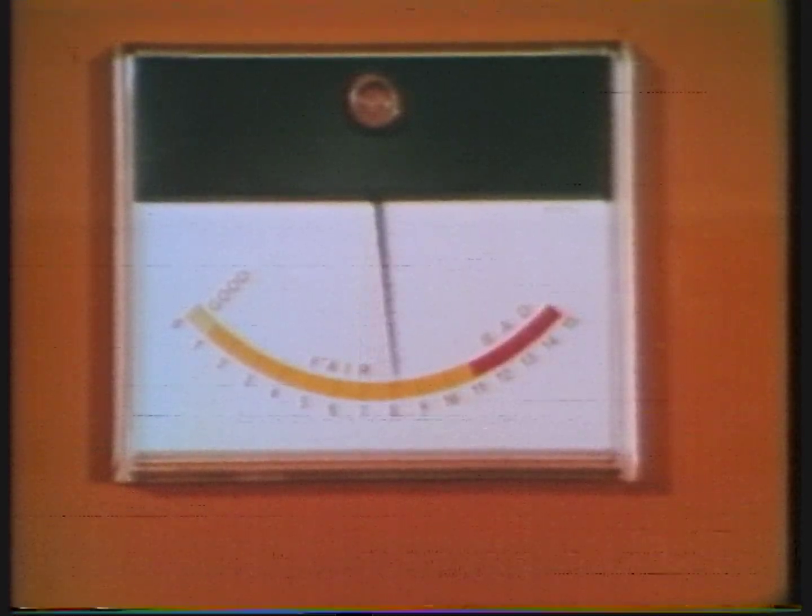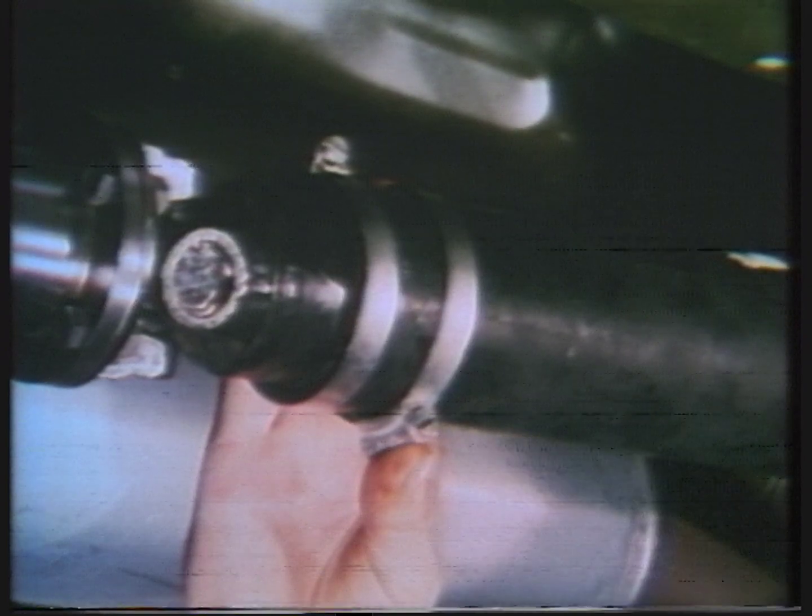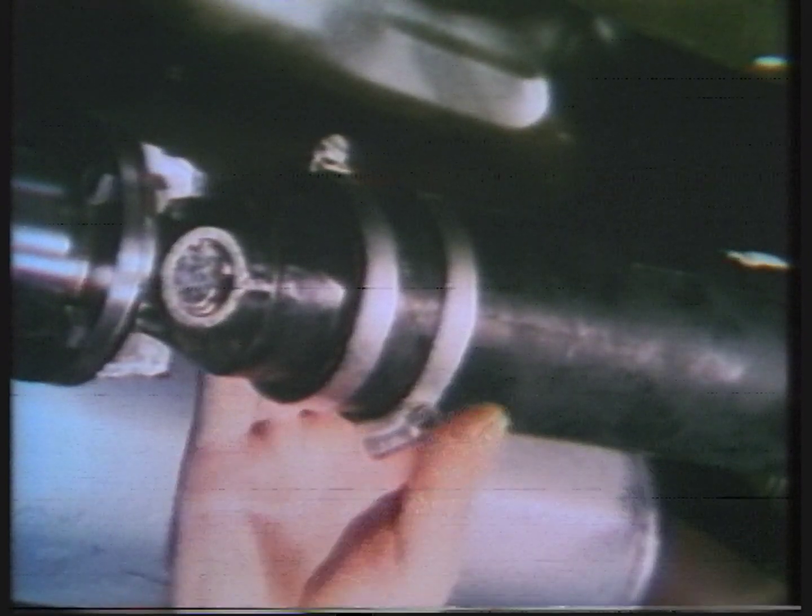The operator now positions the propeller shaft where indicated by the strobe light and fits 1 Jubilee clip with the screw opposite the out of balance position. This will be at the top. The other clip is positioned with the screw at the bottom, 75 millimeters along the shaft, but displaced 25 millimeters anti-clockwise from the unbalance point, which will be at the bottom.